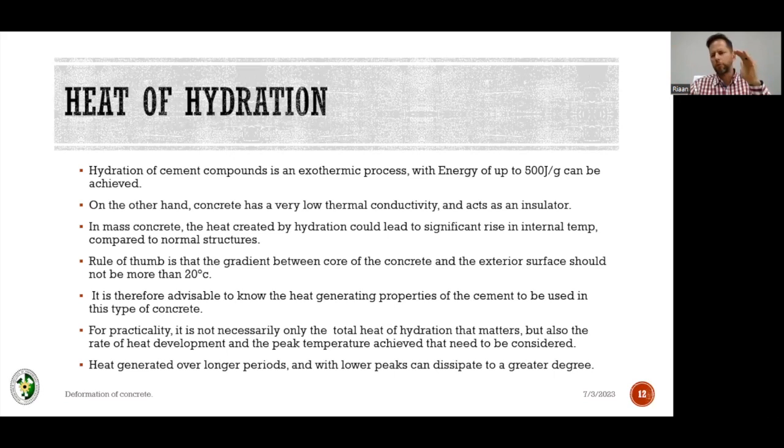It might be maybe 31 on the surface, or maybe a little bit cooler on the surface, but in the core it remains 32. Because it's not being mixed, it's exposing less surface area, and it cannot exude that heat fast enough. So you're breaking the rules that were put down by the consultants of placing at that temperature. So let it mix. It doesn't do the concrete any damage. It actually benefits the performance of your concrete